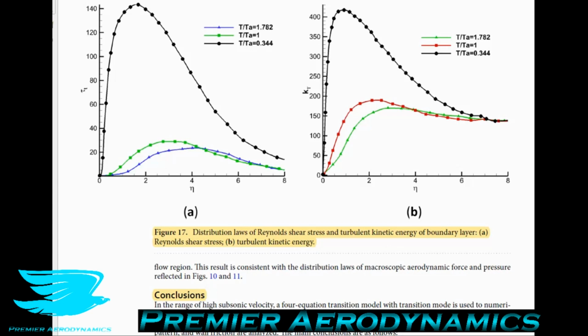That is, the hot wall suppresses the tangential and normal pulsations and stabilizes the flow. So in other words, the disturbances that often create transition, the increase in the temperature of the wall suppresses these features, or suppresses their effects, I should say.